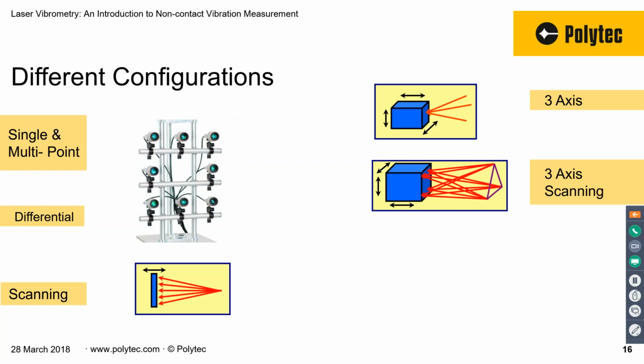And this is our MPV, multi-point vibrometer, that's available in an array of up to 48 lasers that can measure simultaneously. And we can take those signals and make sense of them and provide visualization of deflection shapes, export the data for finite element model validations, and so on.